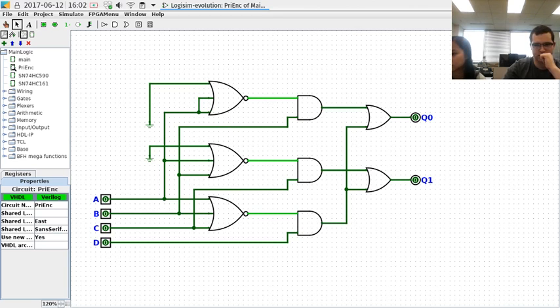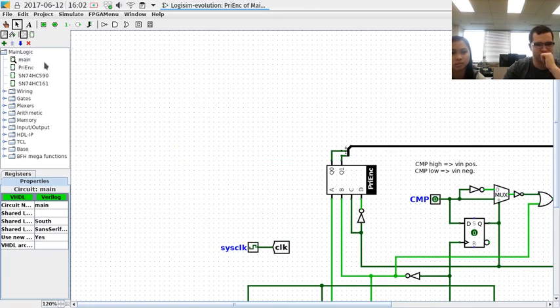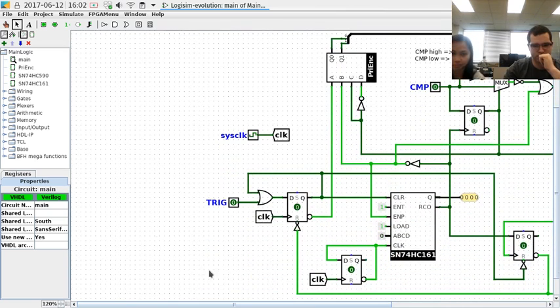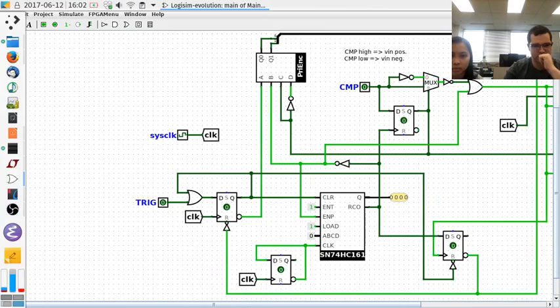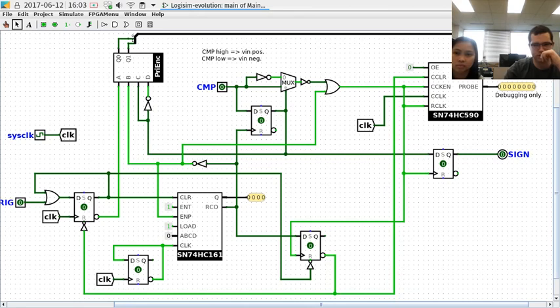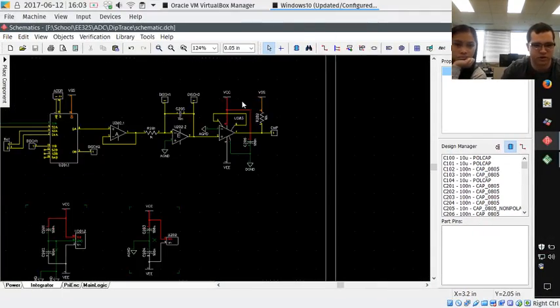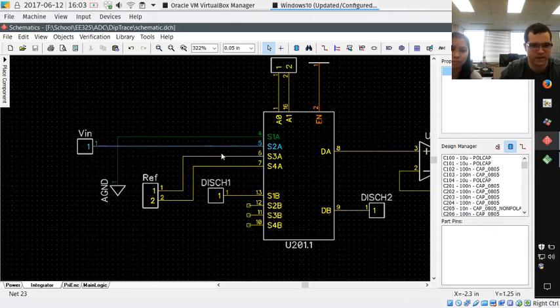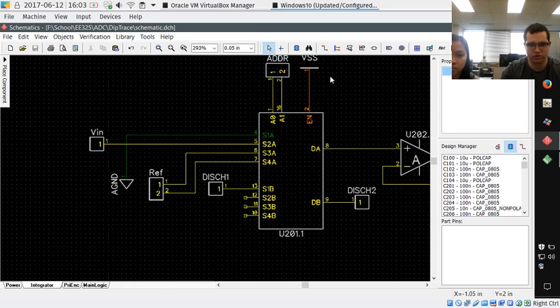And now we're going to the main logic. So this is an early simulation of it here. How this works, the address is the output of the priority encoder, and that's controlling the switch, which, as I mentioned before, is controlling which of these it's going to use: either this analog ground, input voltage, or the references. So those 2 bits there control that.